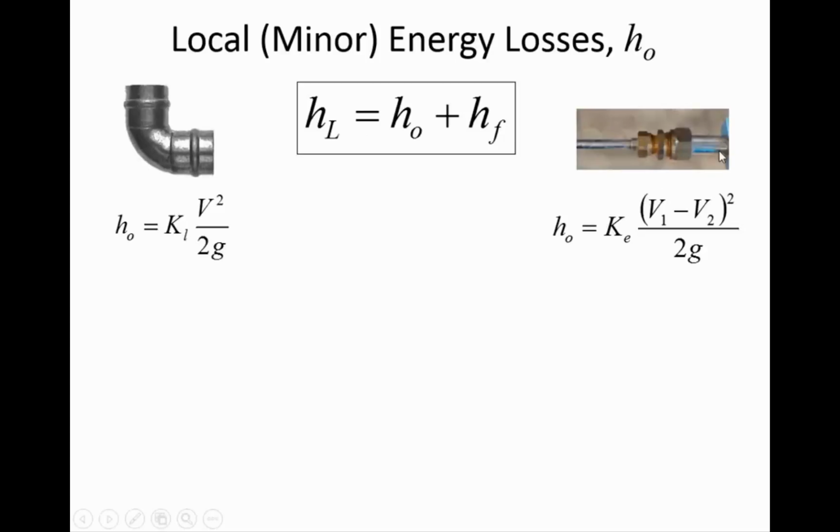It's a little bit different for how changes in diameter are described, and in fact, depending on the manufacturer's data that you get, sometimes the head loss should be calculated just based on the entrance velocity multiplied by some K value. In other cases, they've calibrated the K values relative to the difference in velocity through the transition, so that a small difference in velocity means a small diameter difference and there's not going to be as much energy loss. The bigger the differential, the more turbulence it introduces.